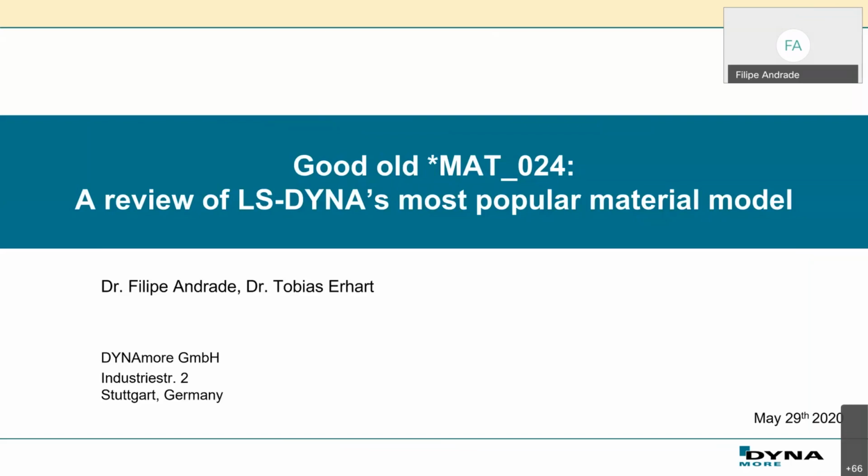I'm not really sure, but especially for crash, of course. For other applications like material forming, you might have other material models that are more popular than Mat24, but anyway, it's very, very often used by LS-DYNA users.